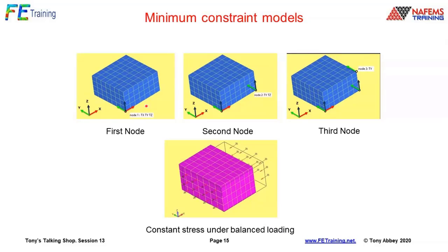Now we shoot down the red axis and we come to some point in here, we intersect that node. If I constrained in the red direction, which is X, I'd lock in strain down in that length. I don't want to do that. So I'm going to put 2 constraints at right angles to that vector, so the green and the red. Now I've stopped spin about Z, the 2 greens. I've stopped spin about the green. That's the 2 blacks, but I'm still free to spin about the x-axis.